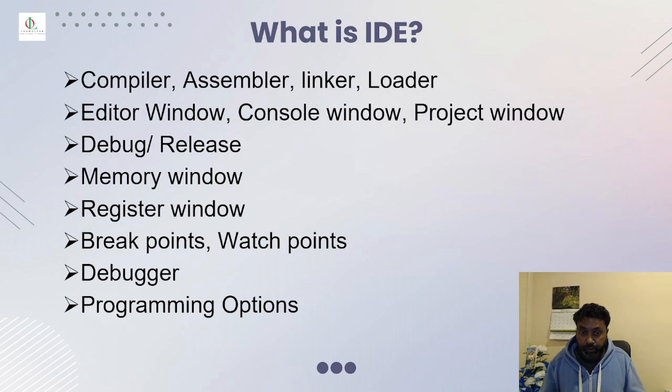And programming options. Some IDEs will have additional options for programming microcontrollers. Some won't, so it depends on what IDE is used. For example, on an 8051 IDE, if you use NXP semiconductors, you need an additional flash programmer to load the boot program, whereas this IDE has built-in functionality, so you don't need an external programmer to program the bootloader.